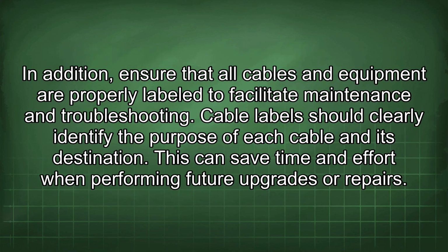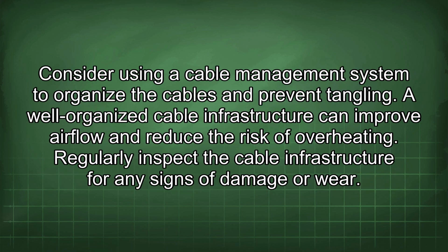In addition, ensure that all cables and equipment are properly labeled to facilitate maintenance and troubleshooting. Cable labels should clearly identify the purpose of each cable and its destination. This can save time and effort when performing future upgrades or repairs. Consider using a cable management system to organize the cables and prevent tangling.